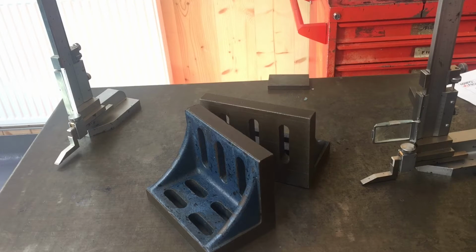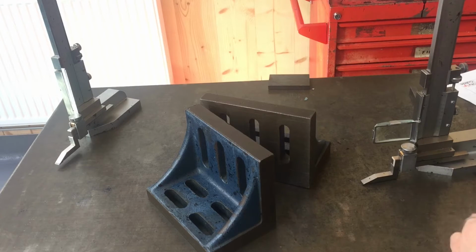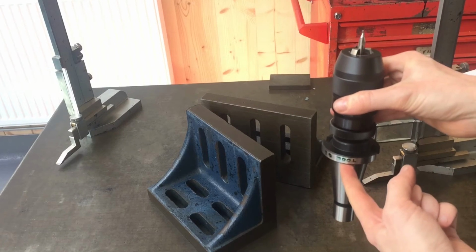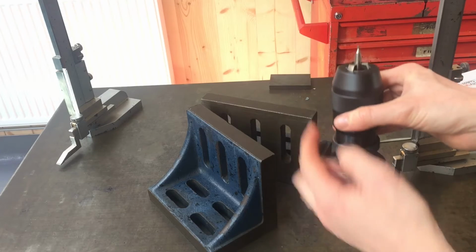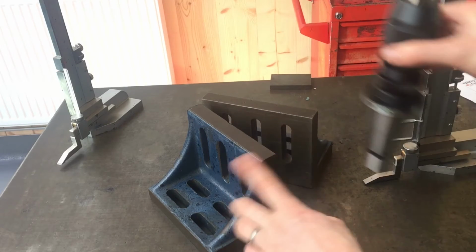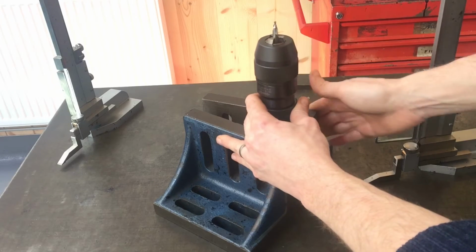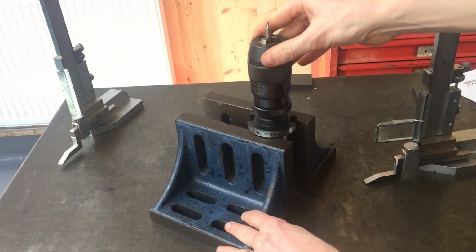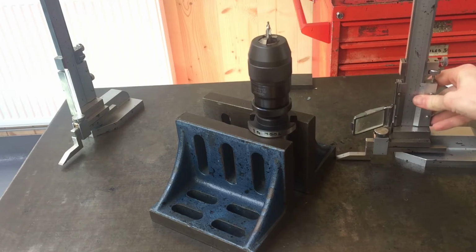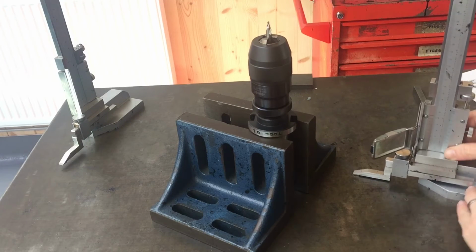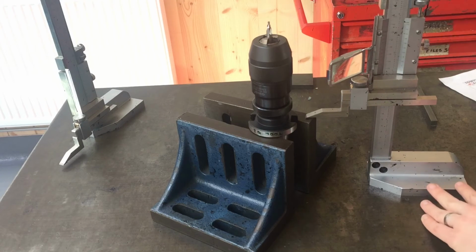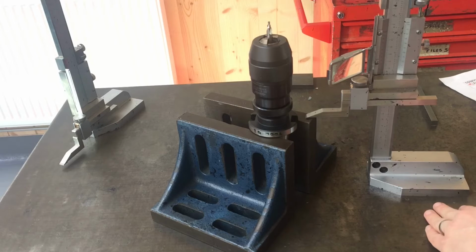So I'm sure there's a whole host of different ways to do this, but the thing that we do here is, if we need to know the TLO, so the distance from where the spindle nose is to the tool tip, we get a pair of matching angle plates that we know the height of, and we set it up between the two plates. And that way we can use a vernier height gauge to take a measurement of the blocks